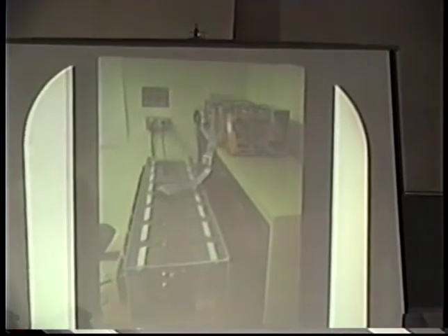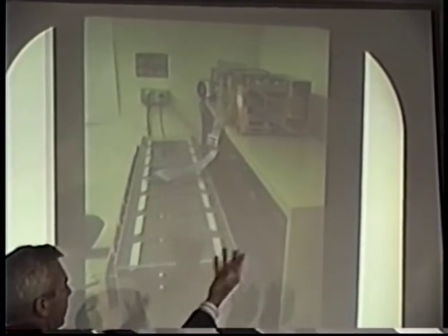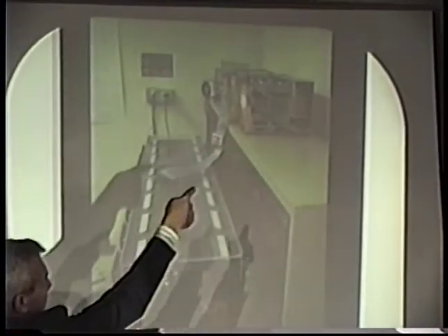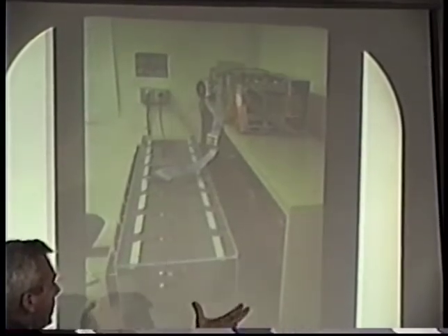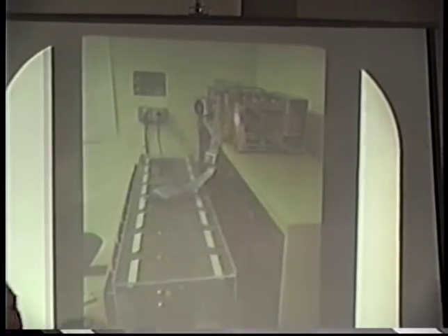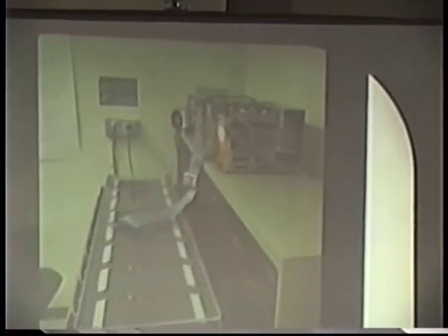And this is a manufacturer's dream. This is just a repeated copy of 64 identical circuit boards in a large card frame. Underneath this, there is a binary 6-cube network, and each one of these computing nodes could communicate with six of its companions in this binary 6-cube. And one of the nodes in the middle had a 7th channel that allowed it to go out to that little host computer.